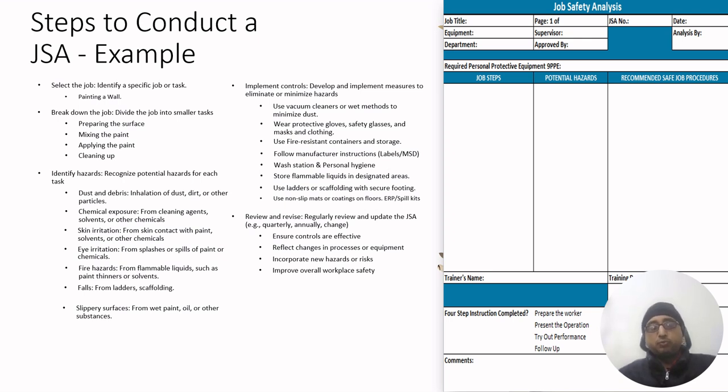Let's see. We should develop a comprehensive procedure to make sure that our lifting plan is sufficient. Also, our risk assessments are suitable and sufficient, and our inspections are comprehensive. Similarly, we have to make sure that the equipment we are selecting is up to the mark as per the requirements, not underrated. Similarly, our staff is certified and authorized to perform the job, and they know how to do it safely.